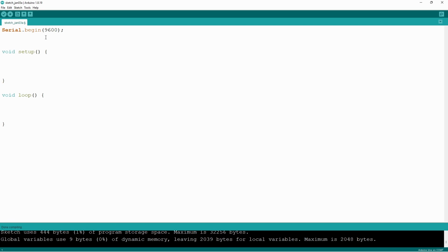Next, I'm going to tell you the 2 other commands. These commands will allow us to present data that has no influence on other functions to the serial monitor. These commands start with Serial.print, and you want to open bracket as well. Obviously, in between these 2 brackets, you want to have double quotations. Within the double quotations, whichever text or numbers you want to write. And the second one is also similar to the previous one, Serial.println. However, with this one, it ends with ln.